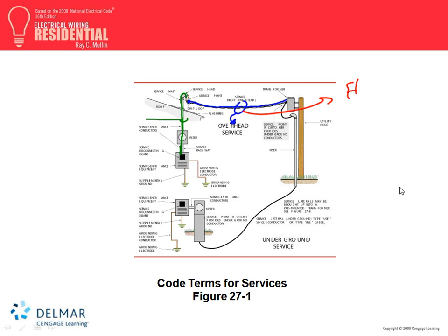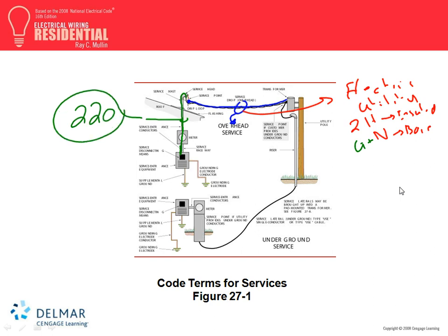So this is the electric utility. Number 1, they give you 2 hots in residential plus a neutral. These are insulated. This one is bare. And they also use the neutral as a ground. In that cable, the neutral and the ground, they use the neutral as a ground. Okay, this one for the service, guys, we size based on 220. Everything that you need to know to size this conductor, we size it based on 220. Yes, sir. Is that the neutral conductor? Yes.